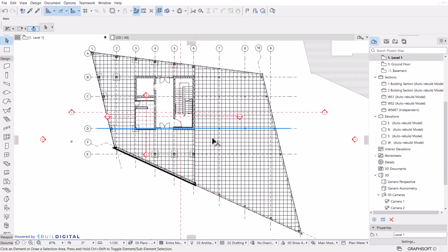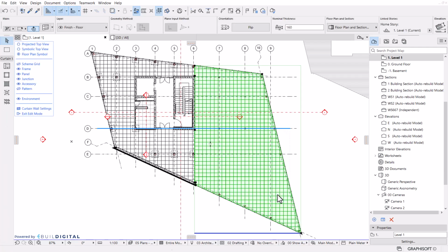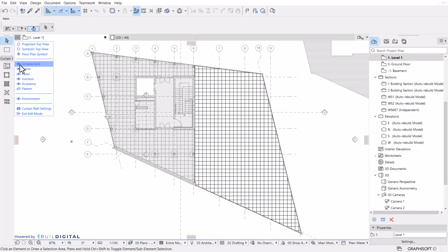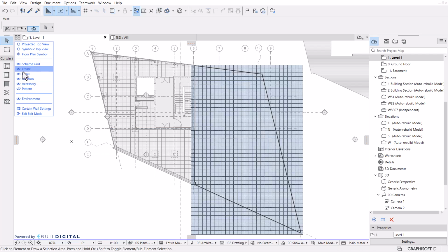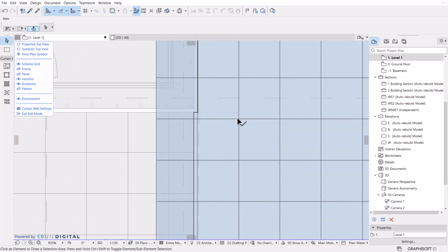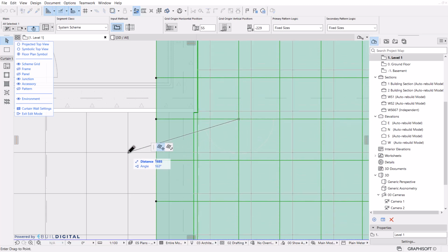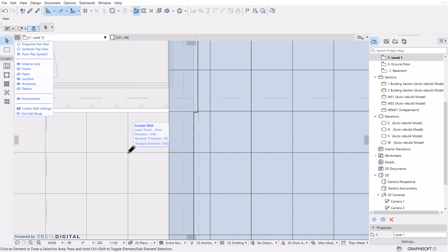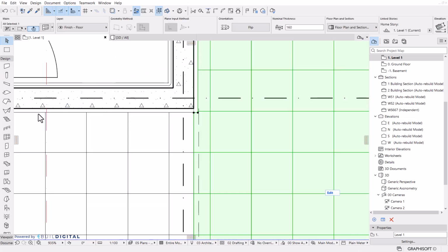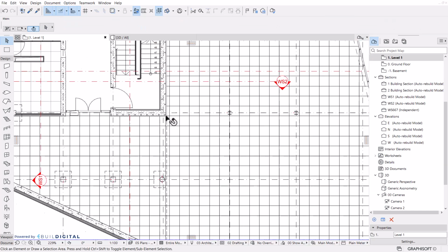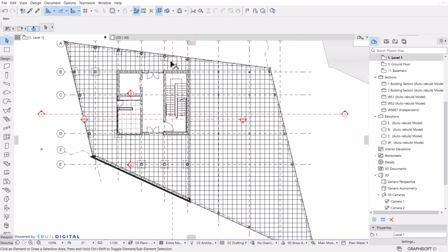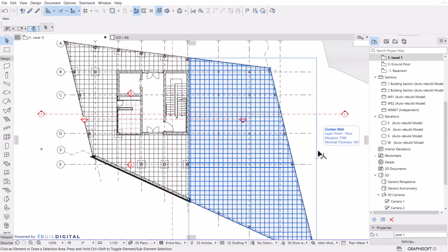Once you're done, if the grid is actually not aligned, now remember that you can align that simply by going into edit mode, switching on the scheme grid of the frames and panels, and simply dragging the intersection to one of the existing intersections, like so, and hit exit. Something like that, and you'll have matching grids across the two floor panels.